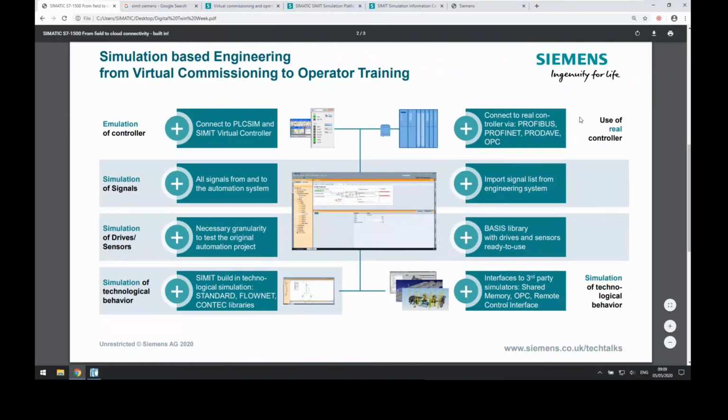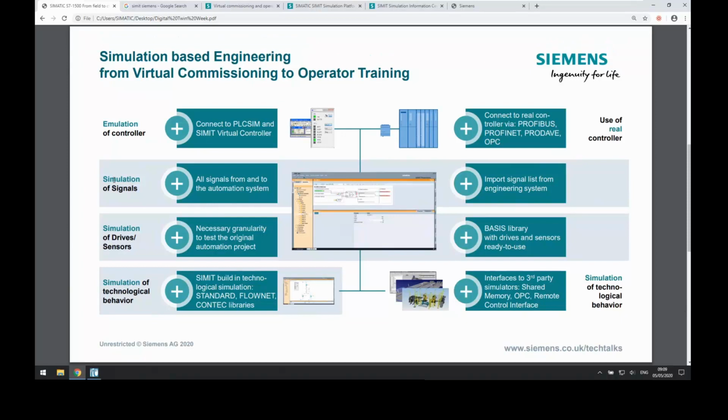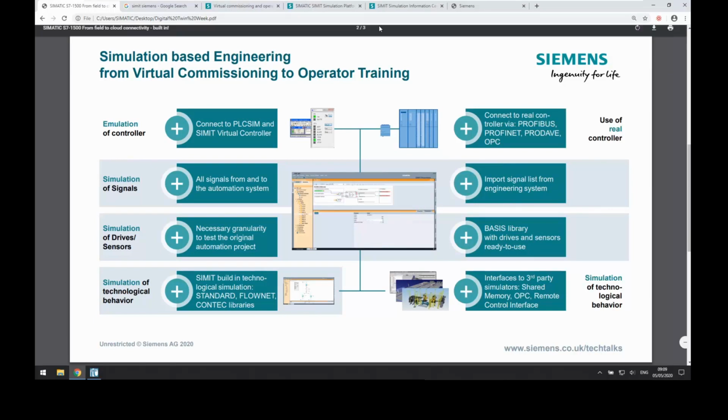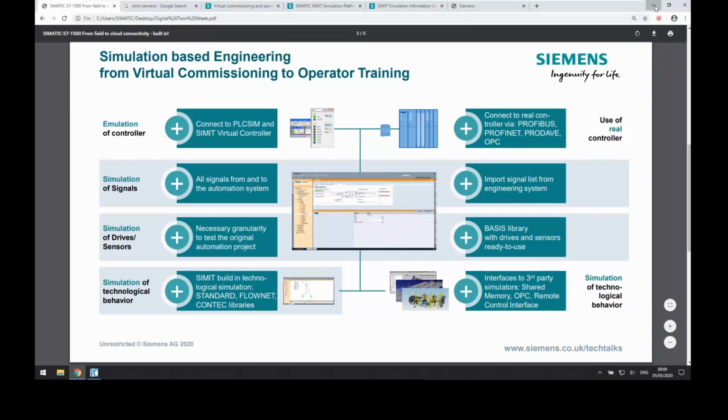So you have some code, you'd like to test it. But this code depends on signals from maybe external sensors, external drives, peripheries, or maybe it reads information from entire technological lines, be it some processes, maybe some external systems. So you are depending on this information in a PLC simulation, and there will be no way for the simulation to progress without getting the data. And this is where SIMIT comes into play. It allows you to simulate all of them. So okay, that's it. No more slides.